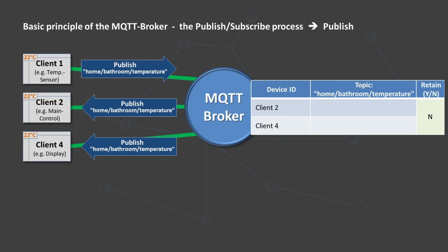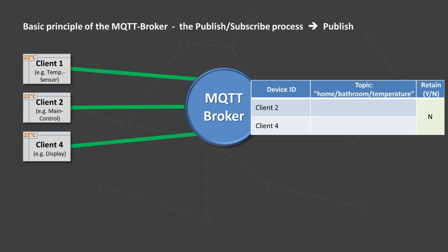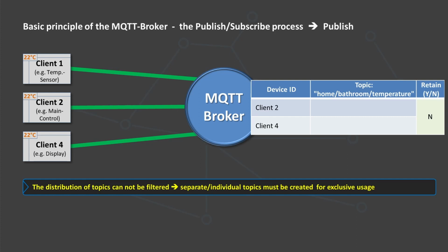The published topics can be of any type or name and can even be new, so that the broker does not know them yet. The broker forwards the messages only when it finds an identical topic in the subscriptions list. It uses no additional decision rules or filtering. It cannot exclude specific subscribers from a particular topic. That is indeed technically possible with some brokers, but extremely complex and effortful for the definition and maintenance of the total system. That's why we ignore this function.